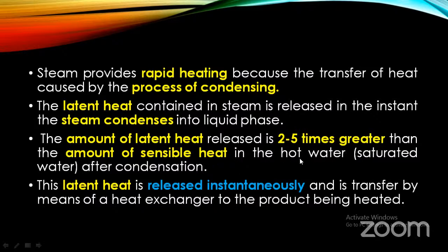If you take hot water for getting the heat energy transferred, it will be only the sensible heat. But if you take steam for the same process, it is the latent heat. When you compare, the sensible heat will be much lower and the latent heat will be higher. This is the main reason we go in for steam as the working fluid, even though the utilization efficiency is very low.